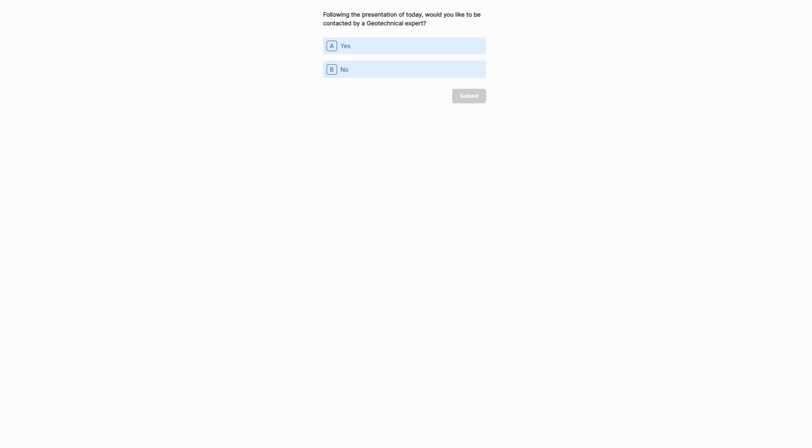The second reason is that if you try to properly evaluate passive force and active force on each side of the wall, I think consideration of the thickness, especially for the passive side onto the soil plug, is more accurate. I had the feeling it was a bit more accurate to proceed this way. No other reason for that. The problem with plate again is that you need to add some specific treatment for dealing with the end bearing capacity.